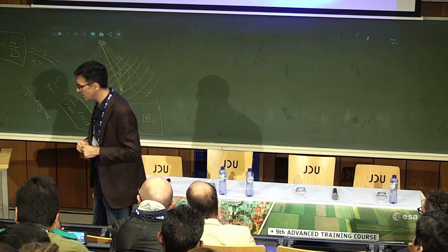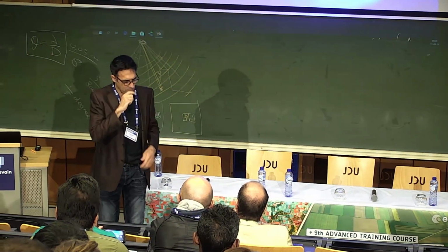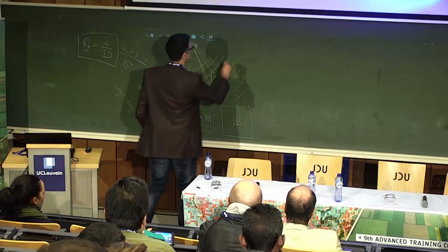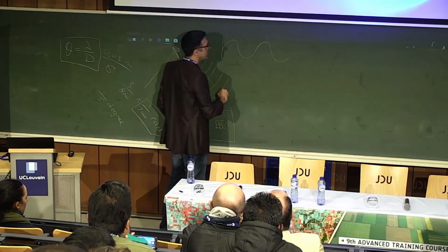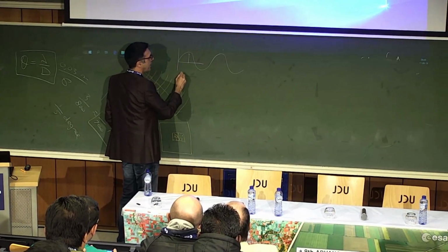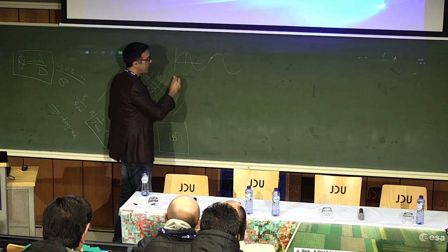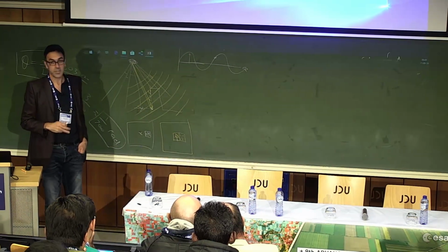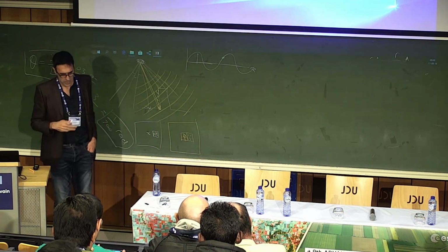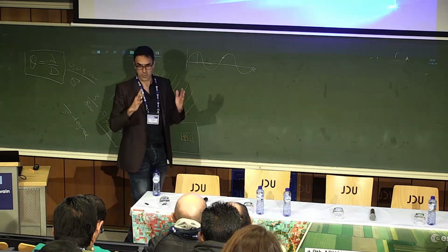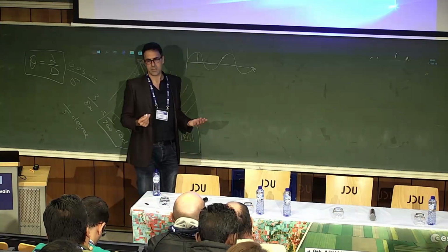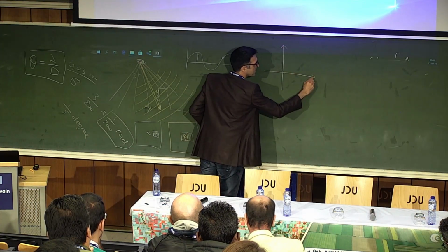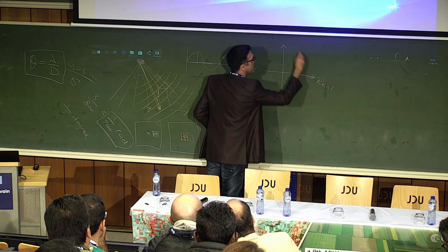So what is going to happen, right? What does the satellite actually get back? Now, what it gets back is a complex signal, right? You know that if we have waves, we can see that as a sinusoid, and the sinusoid has an amplitude, and it has a certain phase, because if I measure it somewhere on this axis, I have the phase, right? So 2 numbers. And these are basically the 2 numbers that I'm receiving from a SAR satellite, from the reflected pulse per resolution cell. And what I do is I denote that as a complex number. So basically, I have 2 axes. We call that the real axis and the imaginary axis.